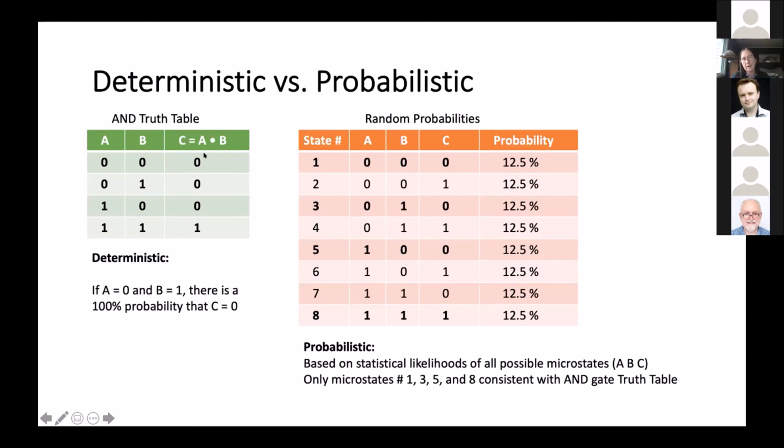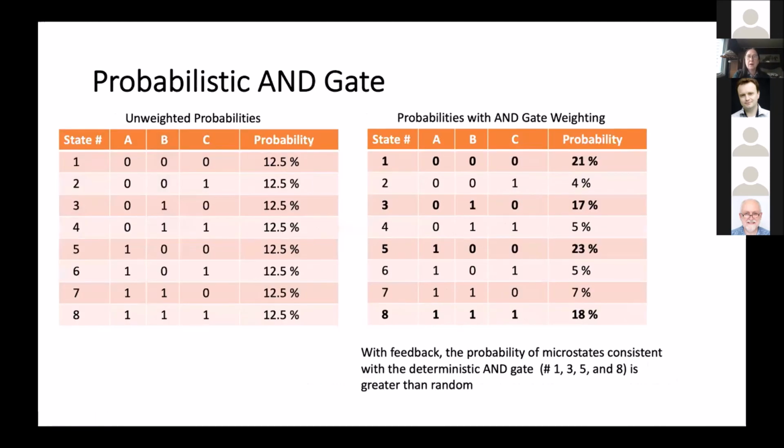So the art of connecting these weights and shifting the set points of the different superparamagnetic tunnel junctions is to try to energetically favor the states that are consistent with a particular logic gate. So here's some data where we were able to do this, and you see that we can definitely shift away from the random case, but we don't get the level of the 95% preference that we did with the NOT gate.